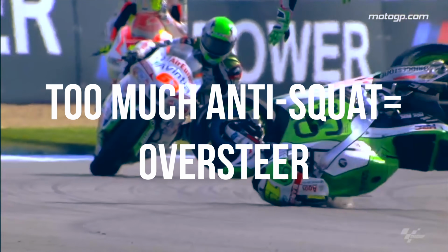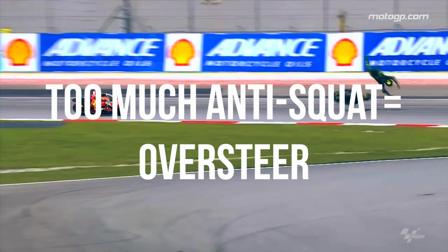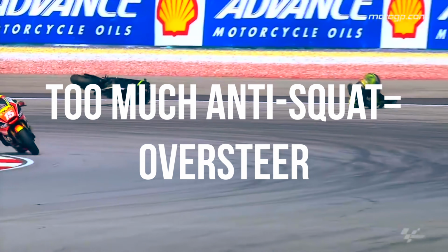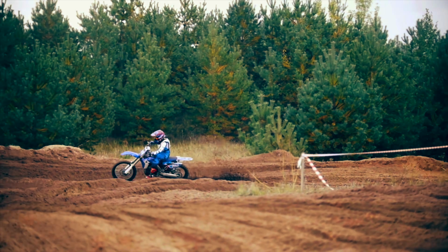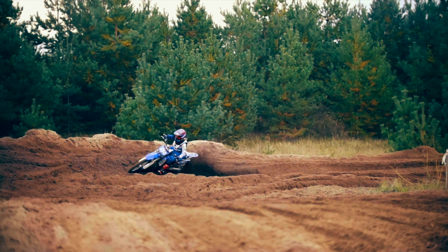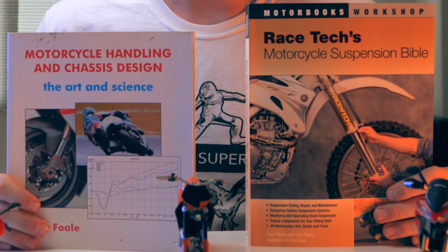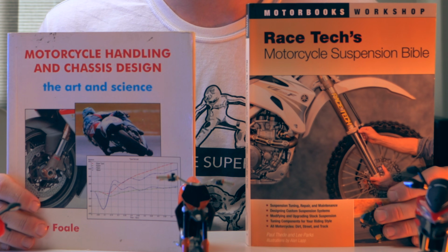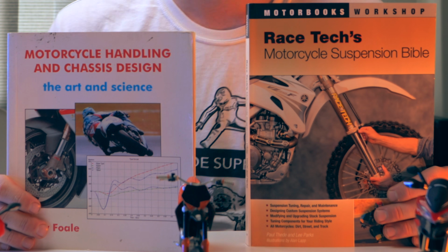If you have too much anti-squat, the center of gravity will move upwards, which will pull the tire away from the ground, resulting in loss of traction, or in other words, the bike will oversteer dramatically. I think you get the gist of it. It all depends on the bike, the rider, the track, and the conditions. The books I recommended earlier provide methods to measure the anti-squat percentage with the bike in a neutral state using various methods.